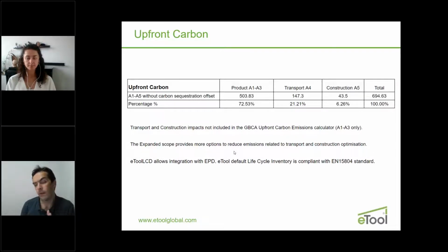And the nice thing about this is that it creates consistency, because the default life cycle inventory and EPDs all follow the same standard, EN 15804. So you create that consistency when replacing inventory data with specific product data, and that's really important for the industry in general to have that consistency.